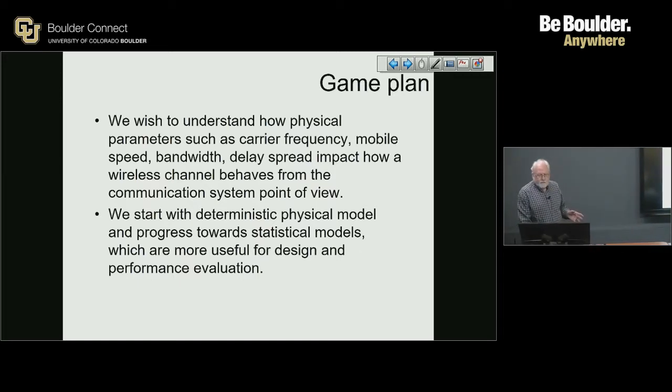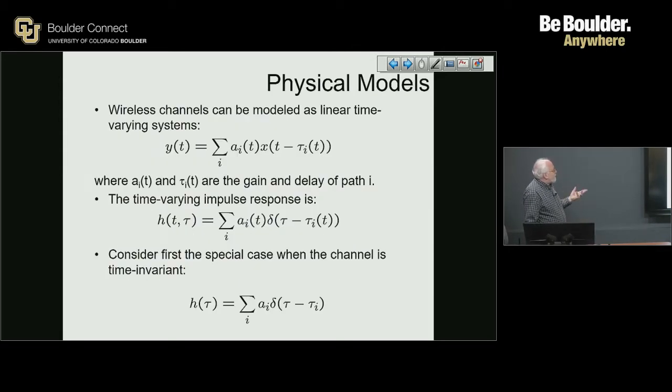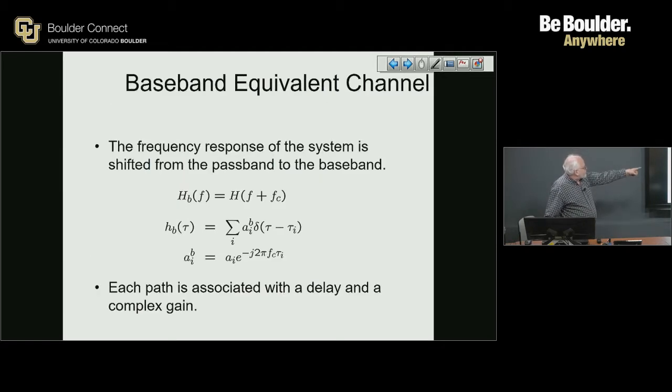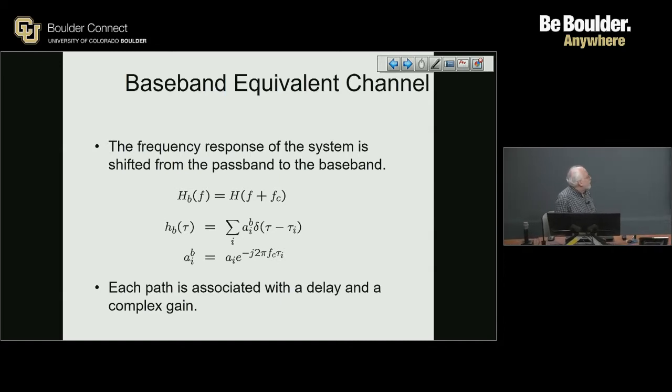And that says we have to come up with a model. We have to come up with a model for, can we model the multipath? Can we come up with empirical models for the multipath? And this is actually what's called the exponential model. If I assume that all these different reflectors are out there and they reflect with different strengths, I can set this up as a sum of different reflections. And that's what ray tracing really does, it tries to calculate a delay and a complex gain for each reflection.